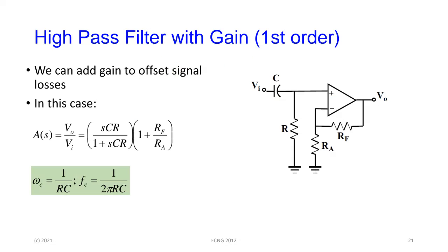And then, of course, what I could do is to add gain to that. So the same thing, notice I have the resistor and the capacitor interchanged, but I can now add an inverting amplifier with gain to it. So here is a high pass filter with gain. Yeah? Fair enough? So questions?